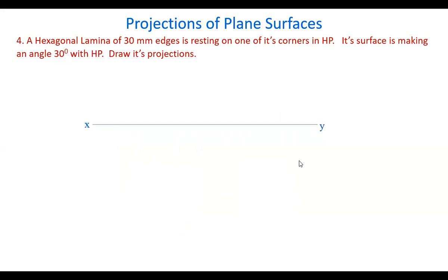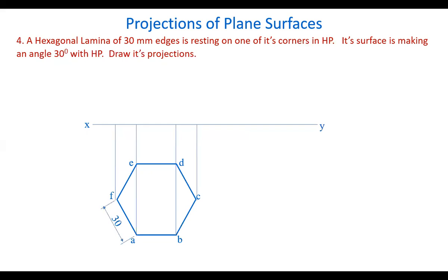Take the horizontal reference line, show the top view such that you get a corner in the left side or right side. Of course, here we got on both sides, we have the corner. There is no problem then. So show the dimensioning. Next, draw projectors from all the points and show the front view here. So F, A, B, C are nearer to the observer. They are drawn normally. D and E are away from the observer from this side. So D and E are kept within brackets.